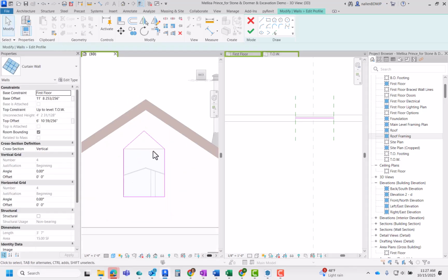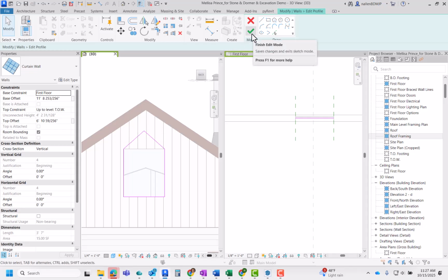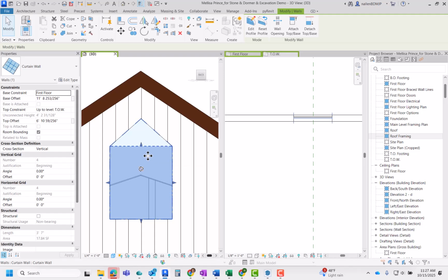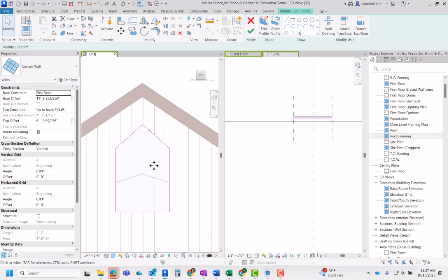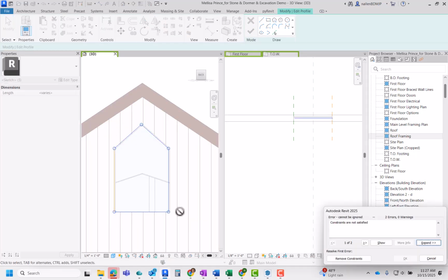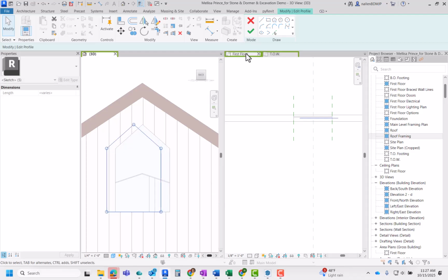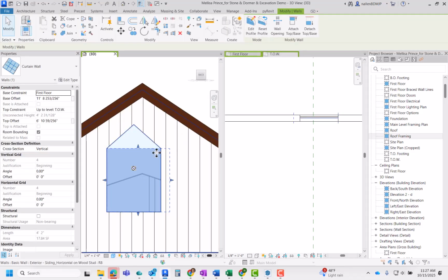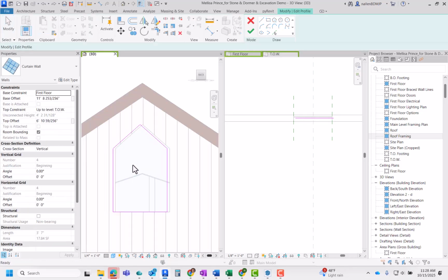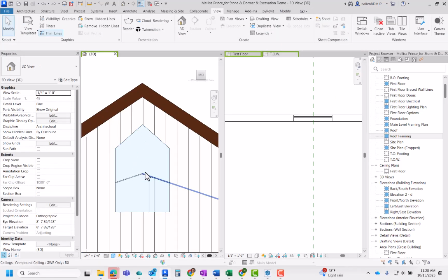Okay, and I don't want to shift the pink lines over. Instead, I'm going to accept this, and then while this window is selected, I'm using my arrow keys to shift it and try to get the alignment. You could move the pink lines, but it will do something kind of weird. You'll see that the window is still actually over here in a sense, even though the glass is over here. So I recommend not doing it that way. The way I just did it now is better.